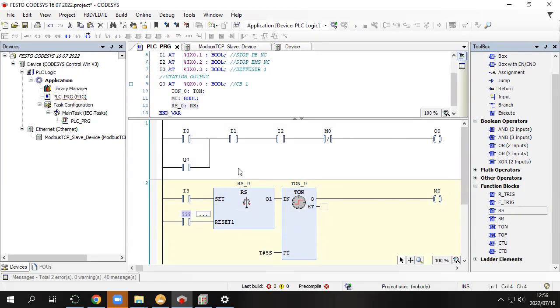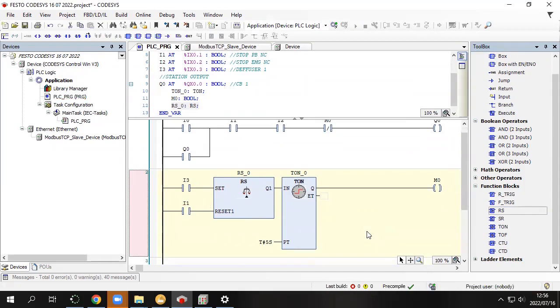Remember, this one is a function block. I'm already tapping into function block. I1. This I1, which is the stop button, is designed to reset the latching relay. The latching relay, I'll give you my own notes, and I'll give you also the notes from Siemens directly. But I recommend you watch my videos. I try to explain them. I try to test them a million times.